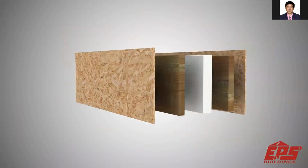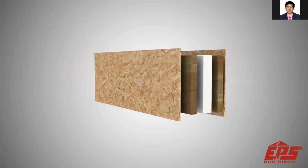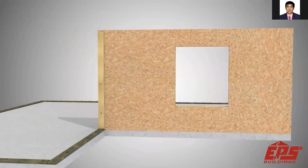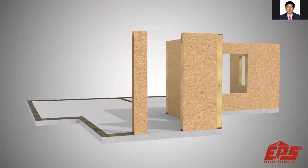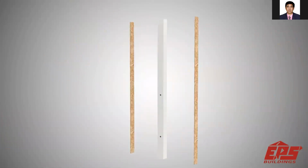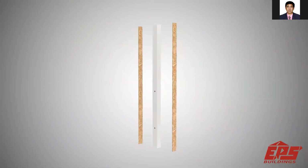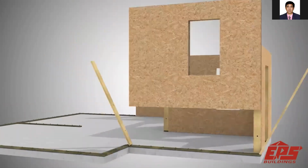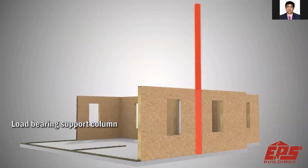EPS packages include pre-assembled factory insulated headers, along with window and door cutouts designed to match each custom designed home. Adjoining panels are connected using a block spline system and approved fasteners. All EPS panels are numbered and marked. This means walls go together quickly as they tilt up and are put in place.